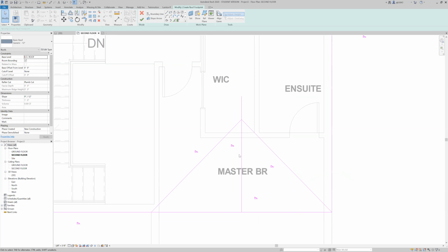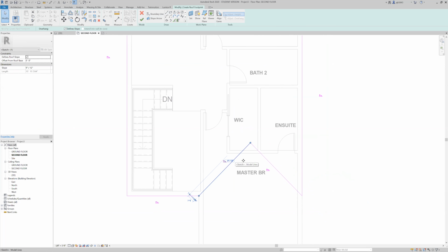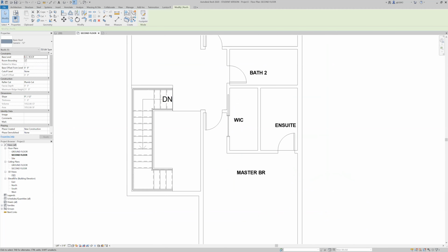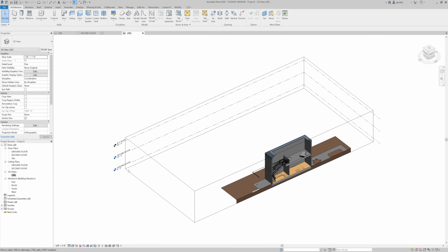And then I'm going to go ahead and delete this line as well as this bottom line. And since I know I want this to vault, I'm not looking for them to define the slope. So I'm going to go ahead and select both of those and uncheck that box. And then go ahead and accept this sketch. Take a look at it. Let's see if I'm right. Maybe.